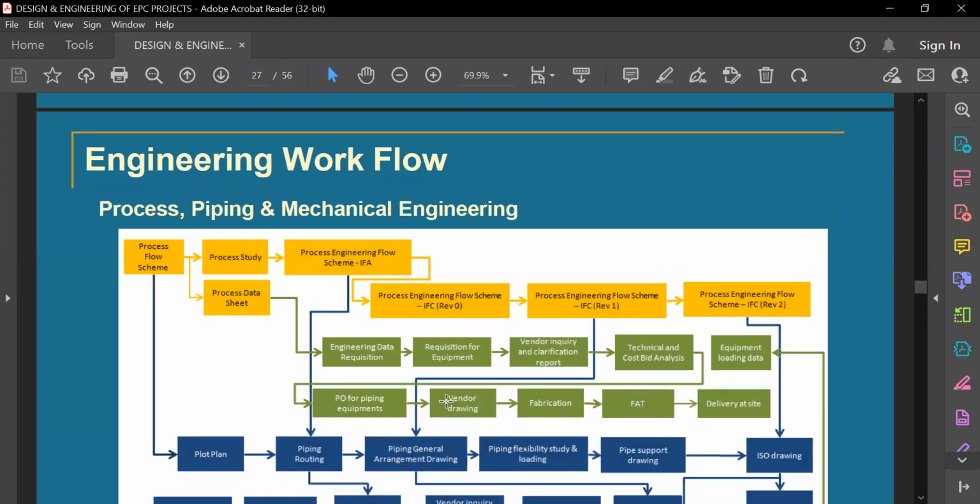So once you are giving a material requisition as an inquiry, floated as an inquiry, then the offer comes. For example, for me, a DCS vendor will give an offer that this is the DCS, this is the PLC as per your account. A pressure transmitter vendor, Honeywell, will give me the data sheet of 5 pressure transmitters which I have mentioned as per the process data. Then I have to review that, and then do the technical evaluation.